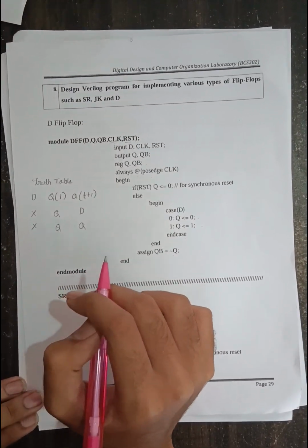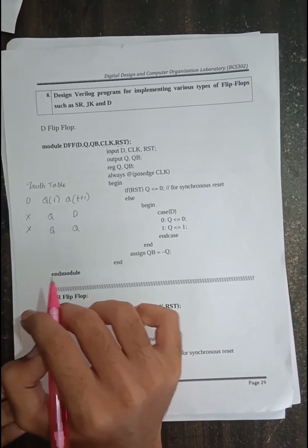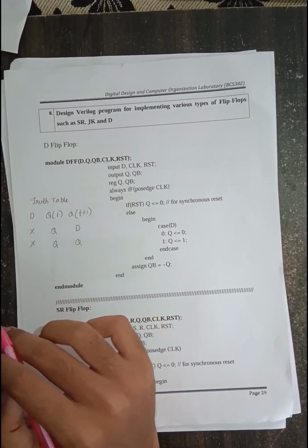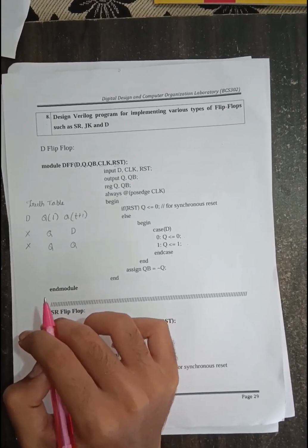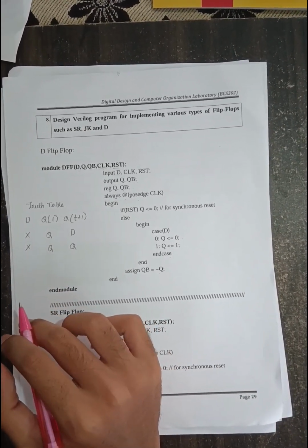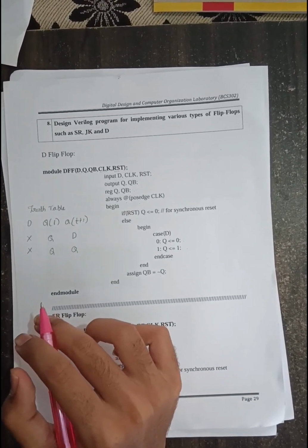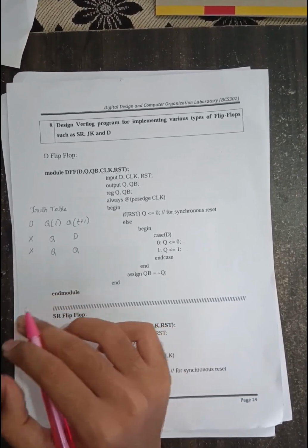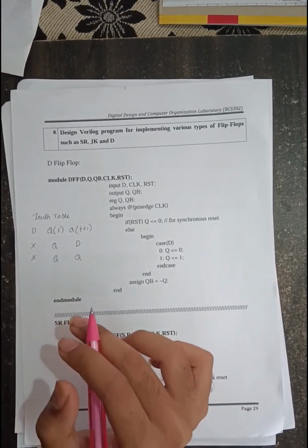Advantages of D flip-flops are: D flip-flop is very simple to design. The computation speed of D flip-flop is very fast as compared to other flip-flops. D flip-flops require very few components to design, which makes it simple to understand. Meanwhile, it also has disadvantages. Disadvantages of D flip-flop are that it is glitch prone. When input varies fast, flip-flop output may change. It is hard to identify and fix it.